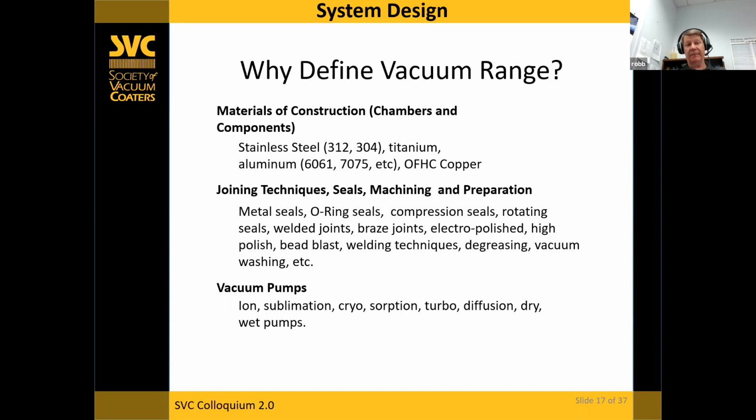Absolutely. So there's going to have to be thought from that perspective as well, because as Duane says, if you put an awful lot of time and effort into getting down to a certain vacuum range, the last thing you want to do is vent that chamber up to atmosphere the next day and then spend another 2 or 3 days baking out and pumping to get back to the original pressure. It's just not practical. Yeah, we've seen that over and over again with different systems.